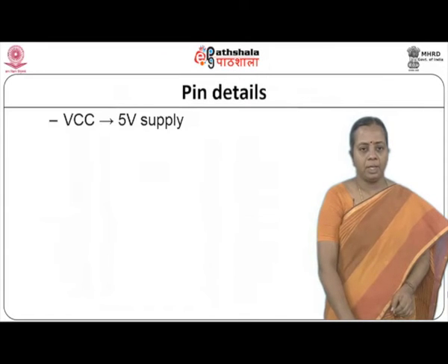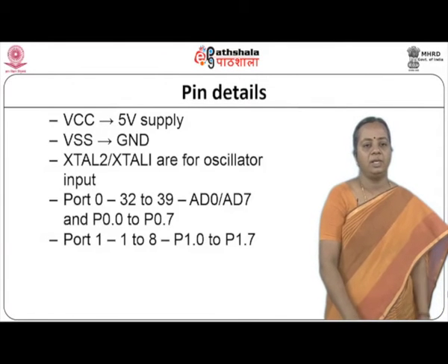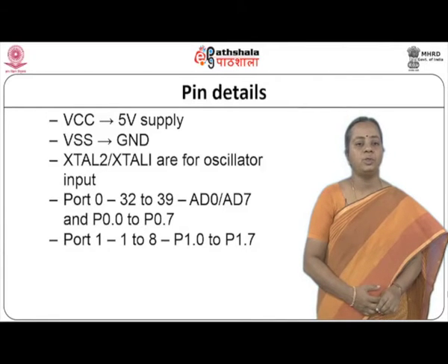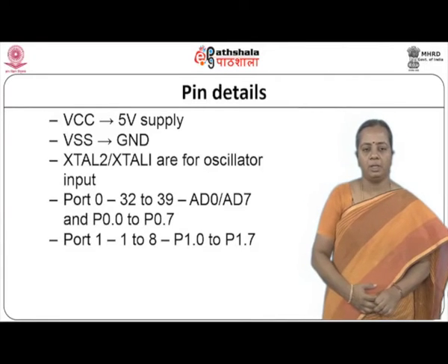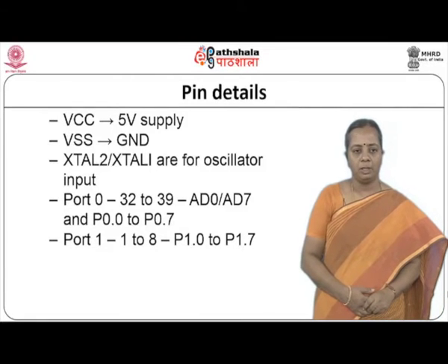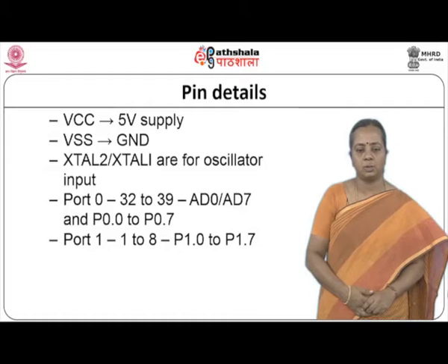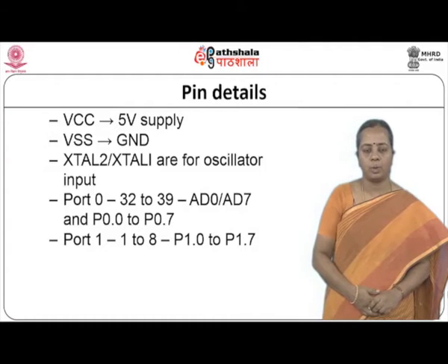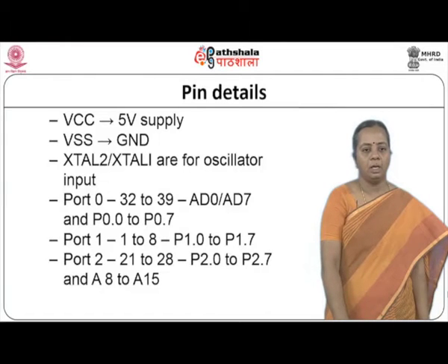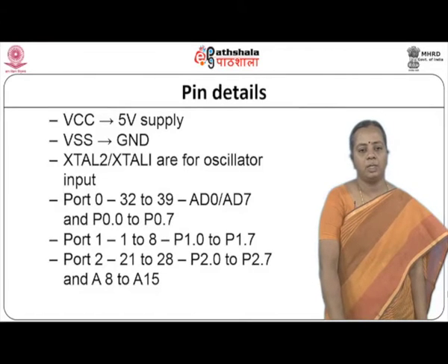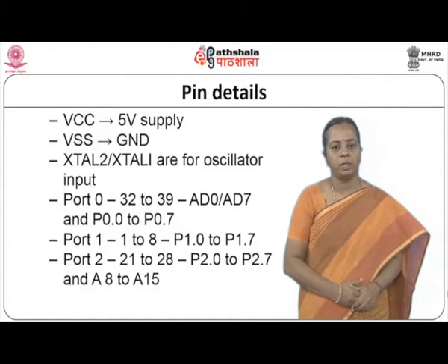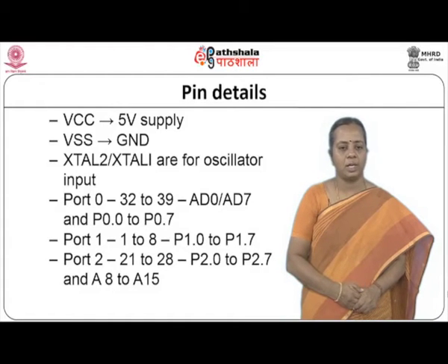When you are looking at the pins, for VCC we have to give a 5 volt supply, and VSS is your ground pin. We have 2 crystal oscillator pins, XTAL1 and XTAL2, which provide the clock to your microcontroller. Port 0 is on pins 32 to 39, and it is a multiplexed port that you can use for address as well as data.